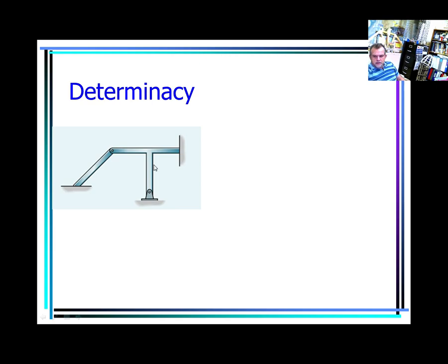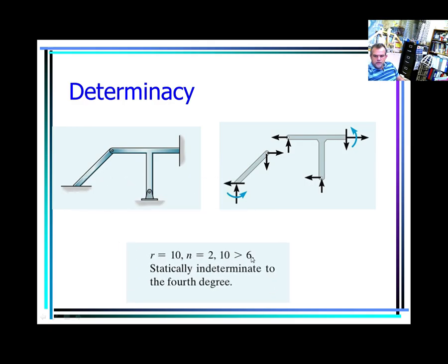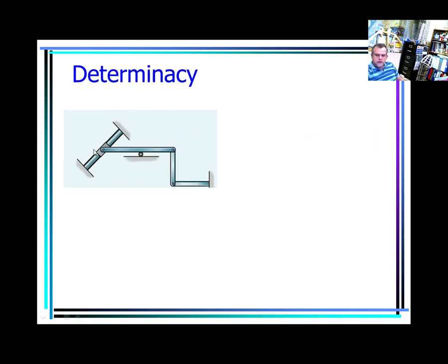Last case, hopefully, for statics, so you have 3, 6, 8, 10, and you have 1, 2, 2 bodies. So if you have 2 bodies and 10, 10 minus 3 times 2, 6, 10 minus 6, 4 degree, indeterminate. This is the same example that we saw before, basically.